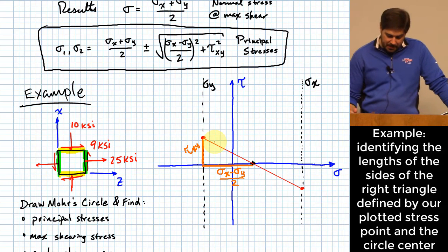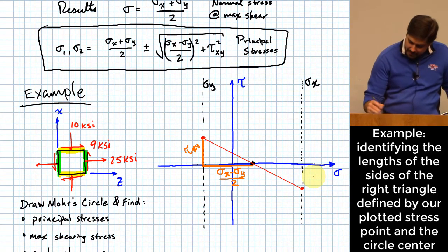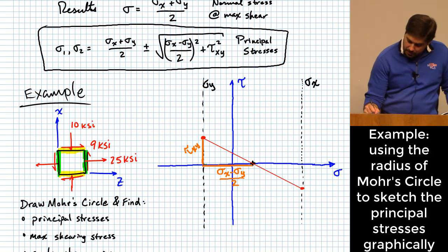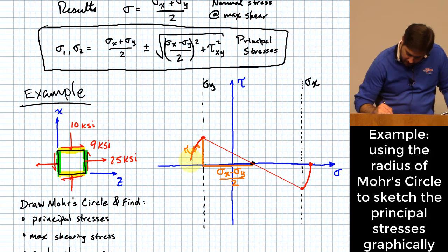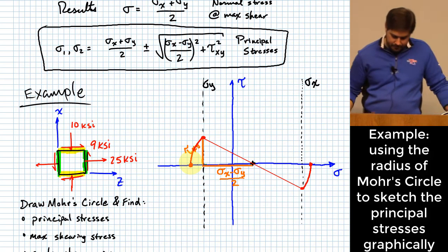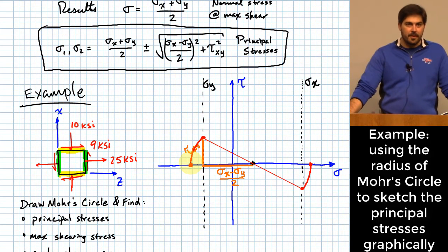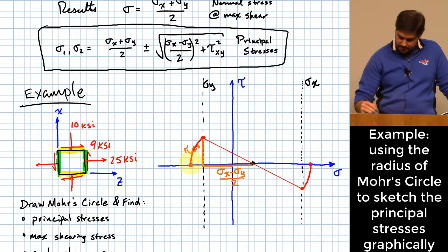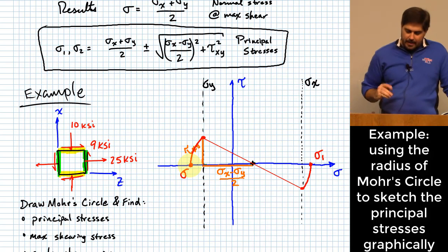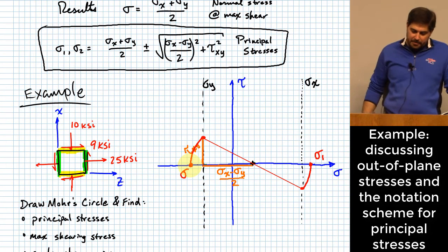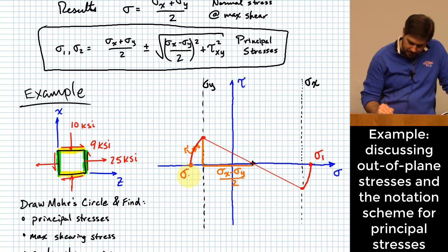Well, that makes sense because essentially what you can say is that's the radius of Mohr's circle. And once you know the radius of Mohr's circle, then graphically, you deal with that by saying, well, I could extend this circle around to the point where I found where it intersected here, or the point where I found where it intersected here. Right? And those would be the principal stresses. And actually, I'm going to use a little bit different notation here. I'm going to call this sigma 3.